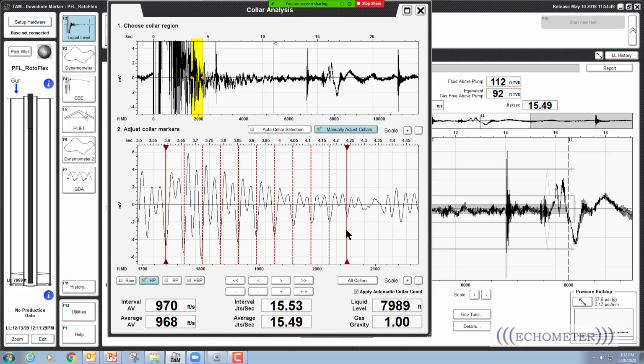There's the well we teach the class at, which is south of Wichita Falls, about 4 miles, the V11 well. We often demo the different gas guns on that well, and the casing pressure on that well is usually about 85 psi. And Ken Skinner frequently shoots the fluid level with the 5,000-pound gas gun, and in a 5,000-foot deep well, you can see the fluid level echo. So 85 psi is probably a low pressure for an implosion shot. And then if you read the manual, it will say if you have 200 pounds of pressure, you can do an implosion shot. So there's not really a physical limit, but to get good quality echo, probably 200 psi or higher differential pressure would be the normal amount of pressure for an implosion shot.